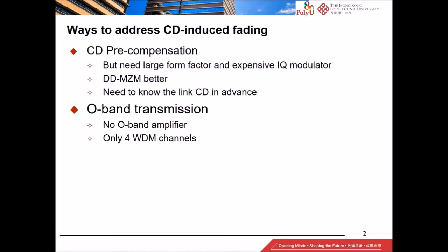Now, however, we don't really have O-band amplifiers, and one of the most recent standards for O-band transmissions will support 4 WDM channels only. So these two things together severely limit how much this idea can scale.